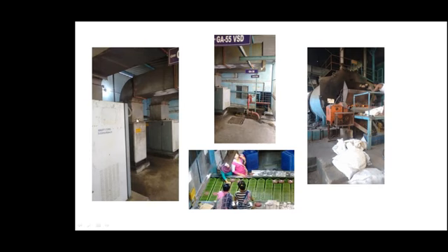So this is a compressor, what you see. An air compressor, the efficiency of the compressor is only 10%. As you generate air, suppose you provide 100 kilowatt of energy to the compressor, the process of air compression generates a lot of heat. So almost 80% goes out as heat. So for 100 kilowatt provided to the motor, you find 80 kilowatt going out through the exhaust air, the ventilation air.